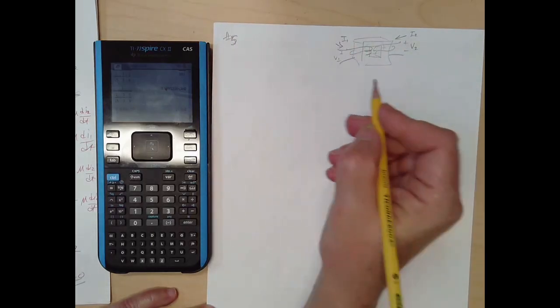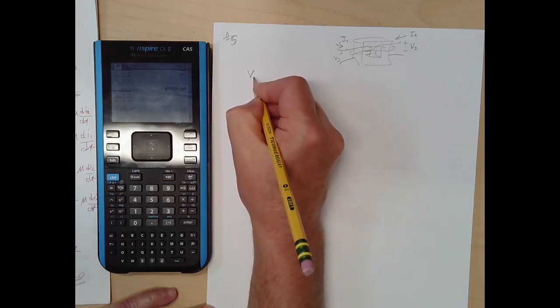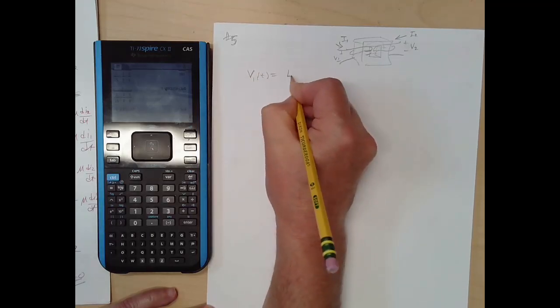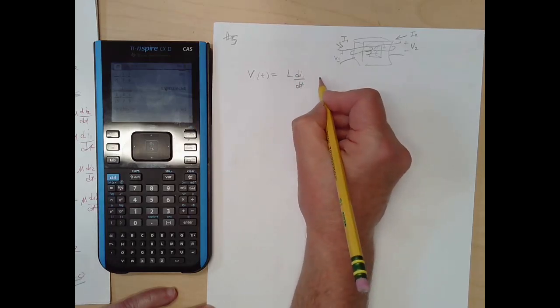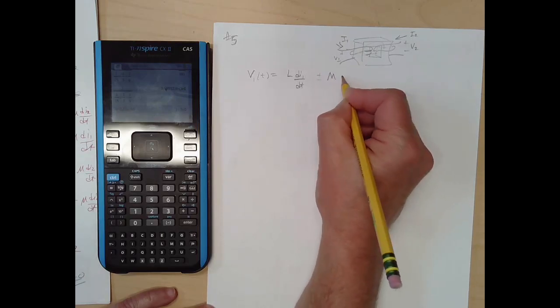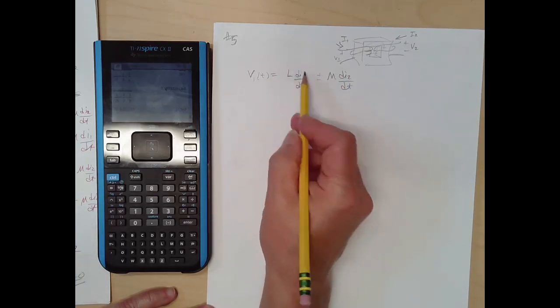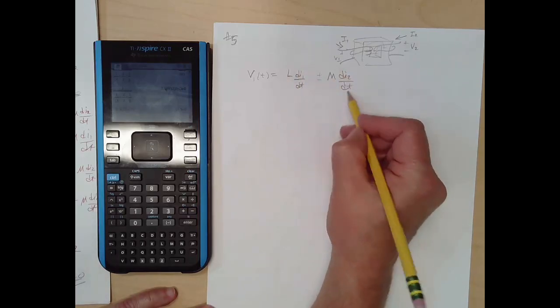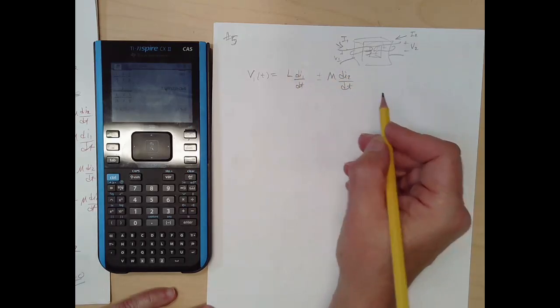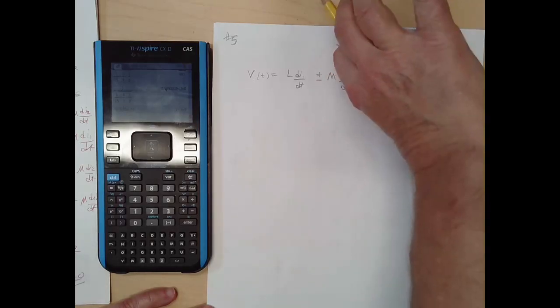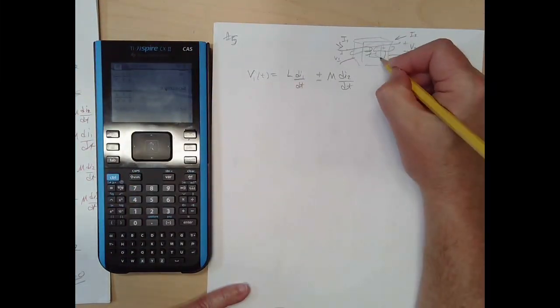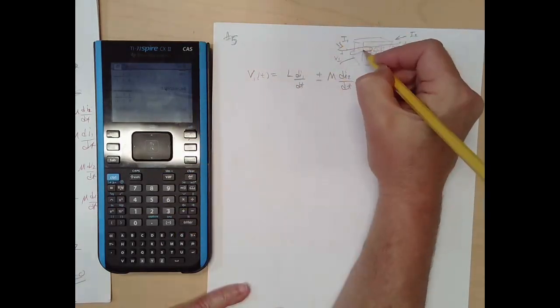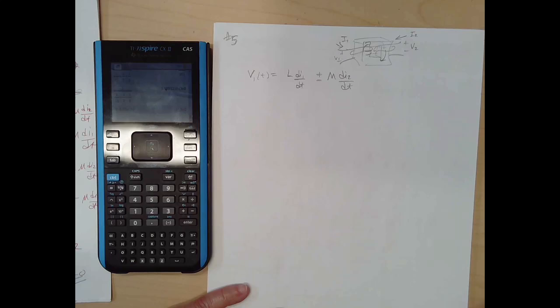Okay, so we will have then, for example, V1. We'll have our normal L di/dt for its own current, and then we will have some, let's just put plus or minus, M di2/dt. All right, so V1 has a component that comes from its own inductance, but then it has a component that comes from the mutual inductance. And the mutual is plus or minus, adding or subtracting, depending on how we put the currents. The way I've drawn this, the first current will try to make a flux this way, and the second one is trying to make a flux this way, so they're actually building each other up, so they agree, so we would have positive.